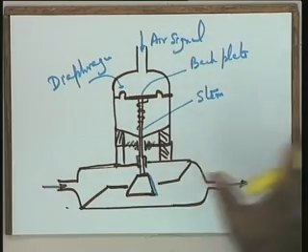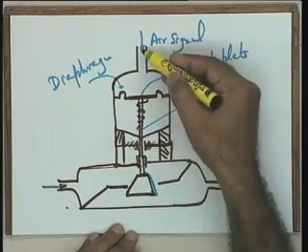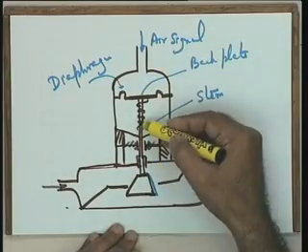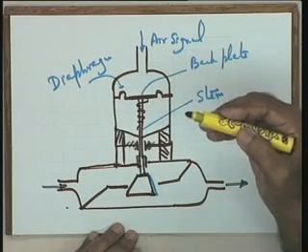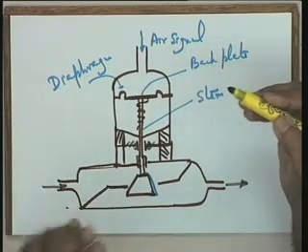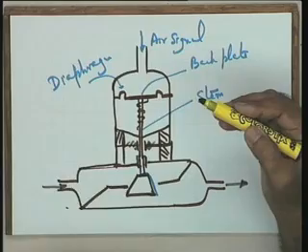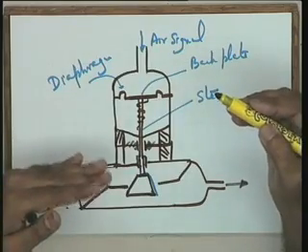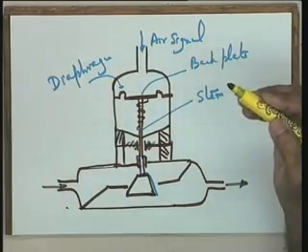The device is highly nonlinear, because the flow versus the stem position and the stem position versus the pressure are nonlinear relationships. But if you consider that your perturbations are small around the equilibrium point, around the steady operating point, then a linear relationship is possible.